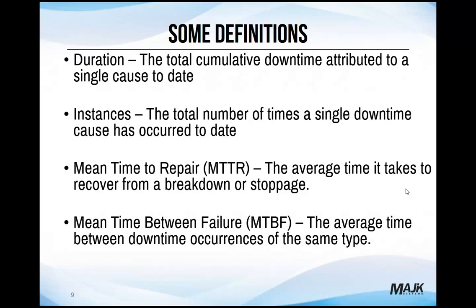Next, we will also look at the mean time between failure. Mean time between failure is a very useful metric for understanding a couple different things. In breakdowns, it may indicate the upcoming failure of a motor or gear as the frequency of the downtime increases and the fault occurs more often. But in the context of today's topic, it indicates our measure of consistency. If we are consistent in how our processes are being performed, both in MTTR and MTBF, it tells us that we have a very stable process.